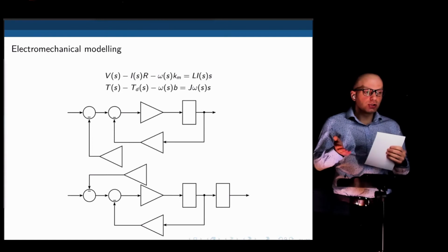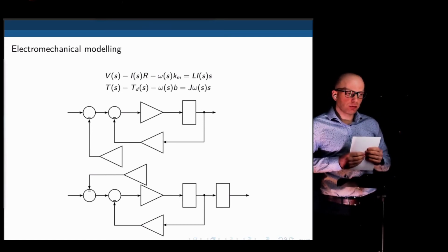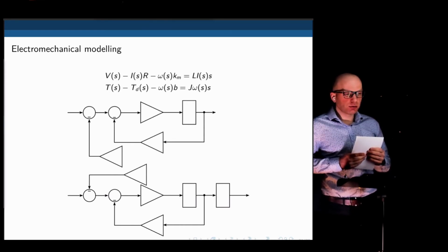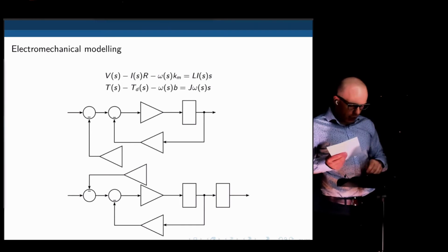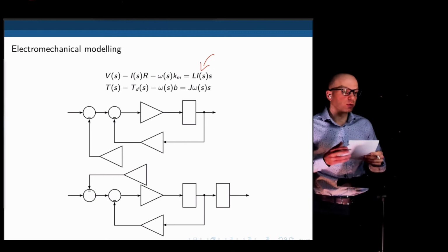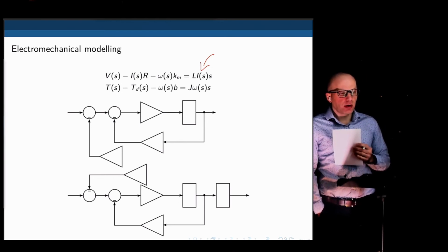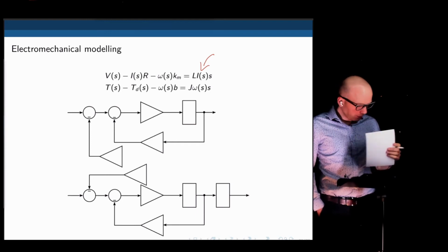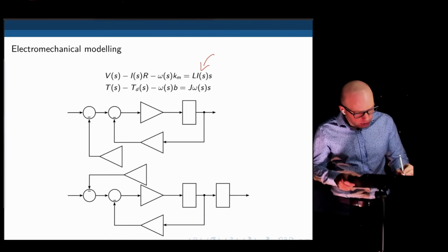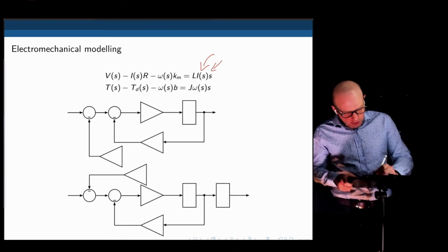So these are the equations for the motor, for the speed, and for the mechanical and electrical part, and we can attempt to do this without any transfer function. To do that, we need to isolate the highest derivative, and the highest derivative that we show in the equations we just calculated is basically Lis times S. We can start from the input in the first equation and create an expression for this element with the highest derivative. That would be V of S